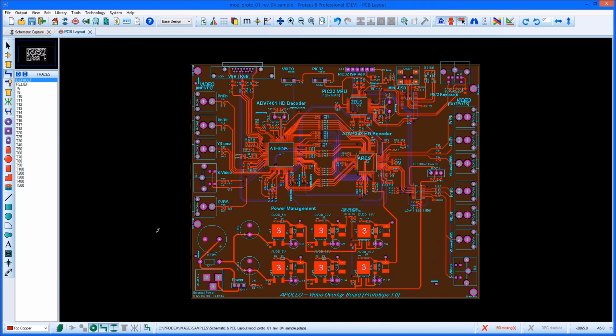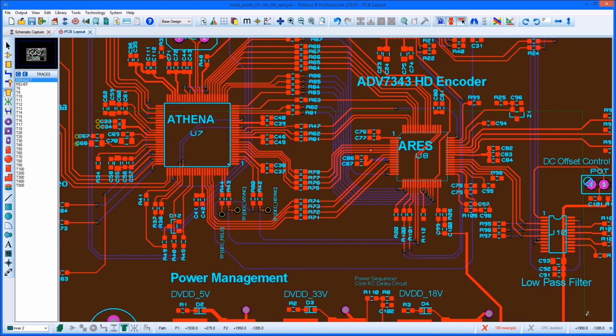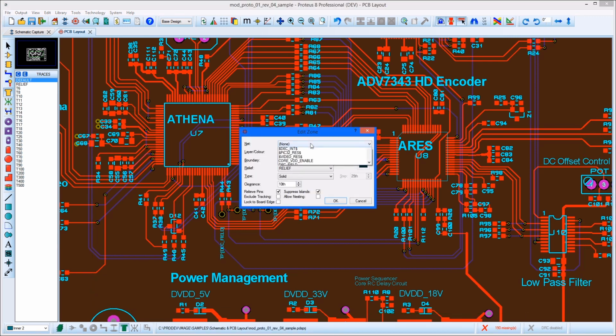Users with a level 2 or higher can also create split planes on plane layers by drawing them manually. First, select the powerplane icon, change the layer selector as required, and then use consecutive left clicks to map out the area of coverage. Configure the dialog as required and hit the OK button to commit placement.